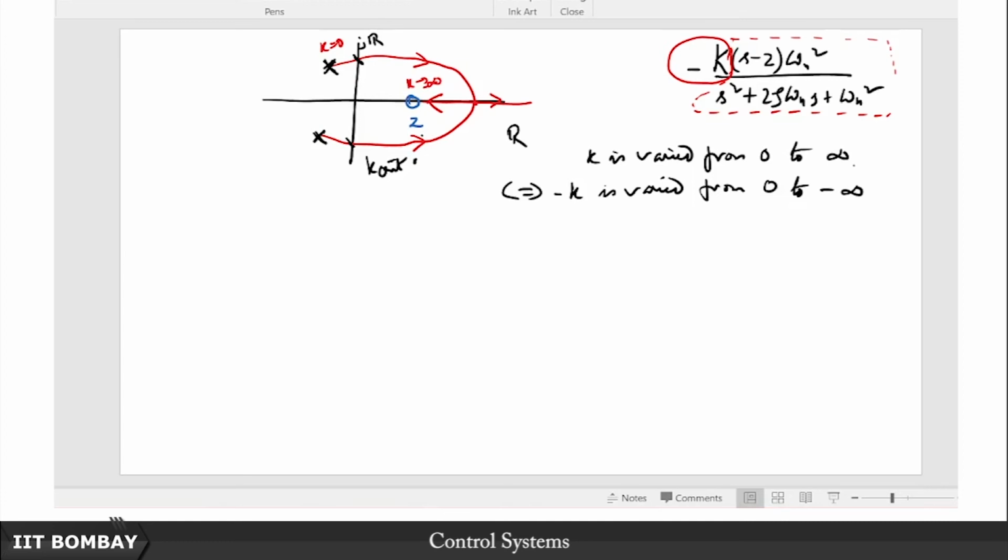See, I have not given any numerical values here. Just based on the rules of root locus, I have sketched this rough plot of what the root locus might look like. I mean, for all I care, this might have actually gone like this. I don't really care. Of course, things are generally nicer, but they are both telling me the same story, which is that beyond a certain value of k, you better be careful because the closed loop poles are going to migrate to the right half plane and remain there thereafter.